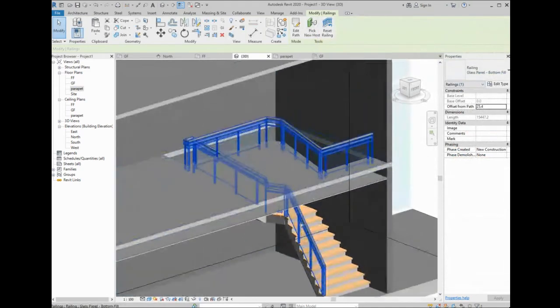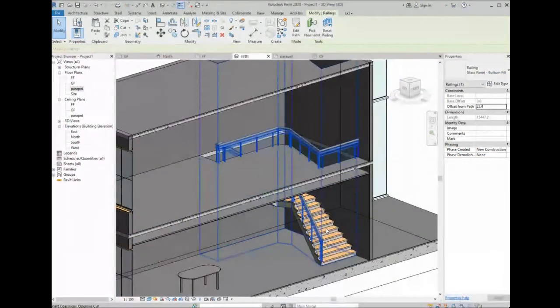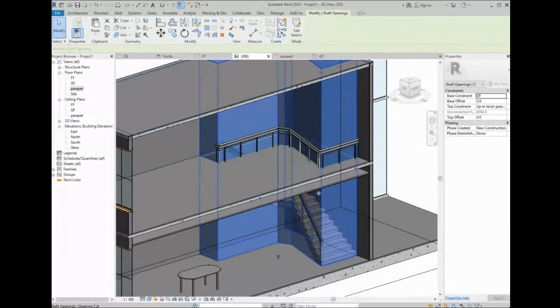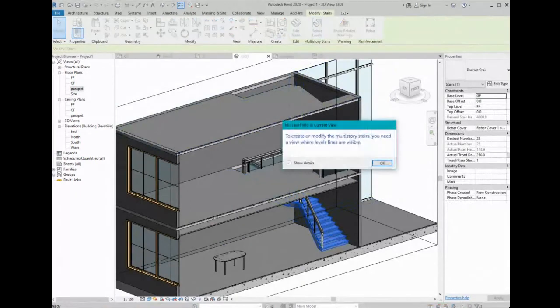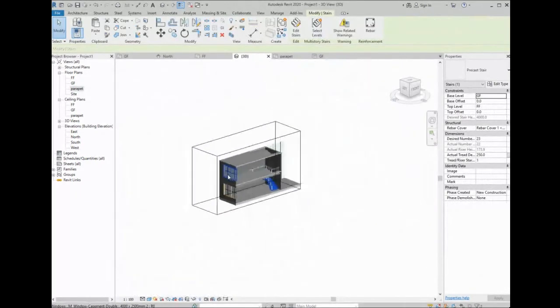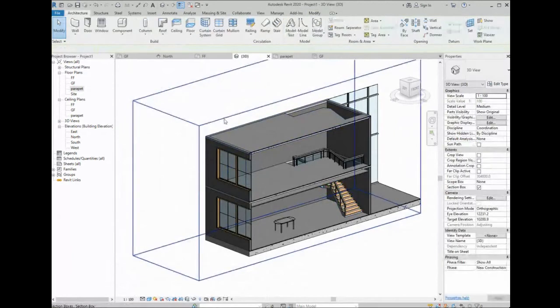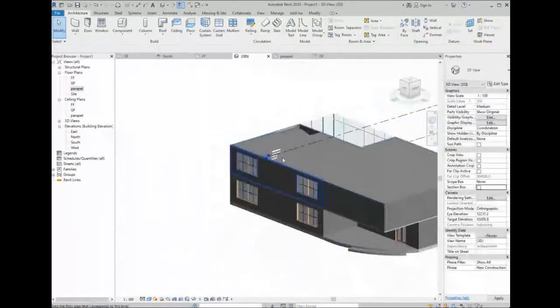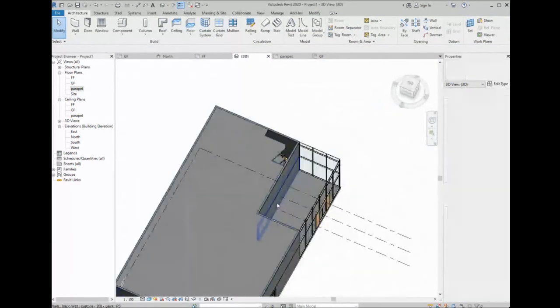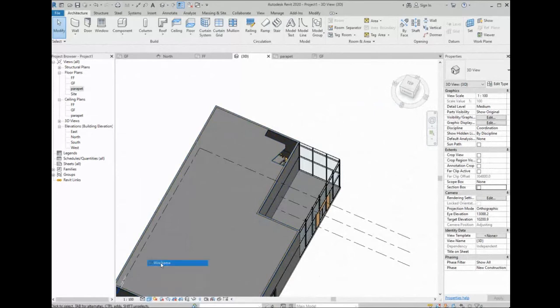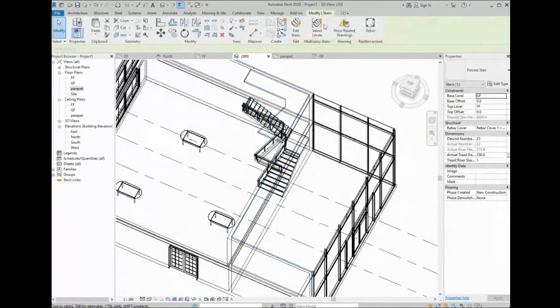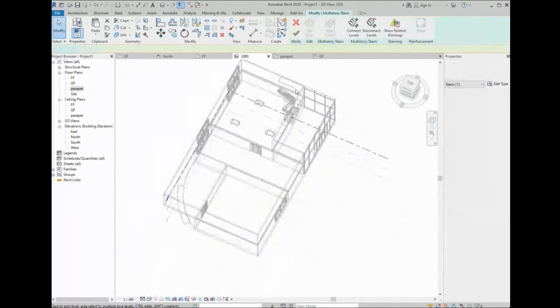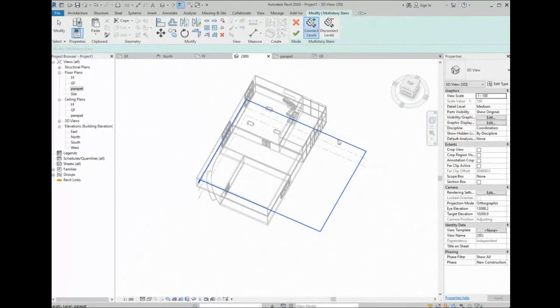Okay, so at the end you will reach your design. When you are done, you will select the stair, and then you will go to select levels. Okay, and you will select the levels. So to select levels, I will just remove this one section box so I can see the levels. Of course, you can always go to wireframe, so you can select things from inside. I don't want the shaft, I want this one. Select level, and I will select this level.